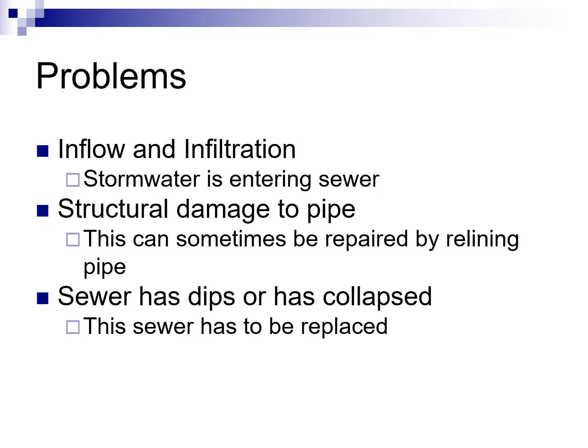Then sometimes I might have a sewer that has collapsed or has dips in it, and in that case I do have to dig it up and replace it because I cannot line it if it's collapsed.